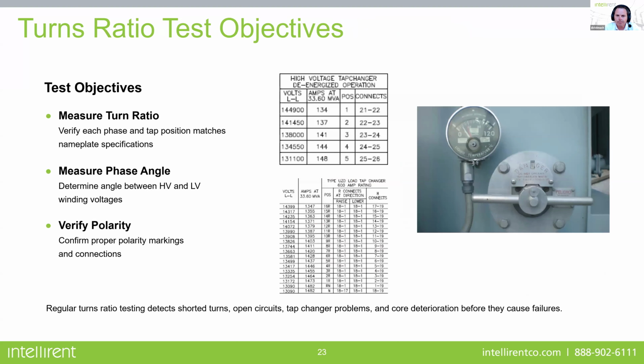And speaking of taps, there's what's called a de-energized tap changer and an LTC. De-energized means you cannot move that tap changer unless it's de-energized. And you have to really be careful because a lot of customers or a lot of utilities do not want to ever move that de-energized tap changer. Typically there's a lock on it and it stays in that place where you put it.